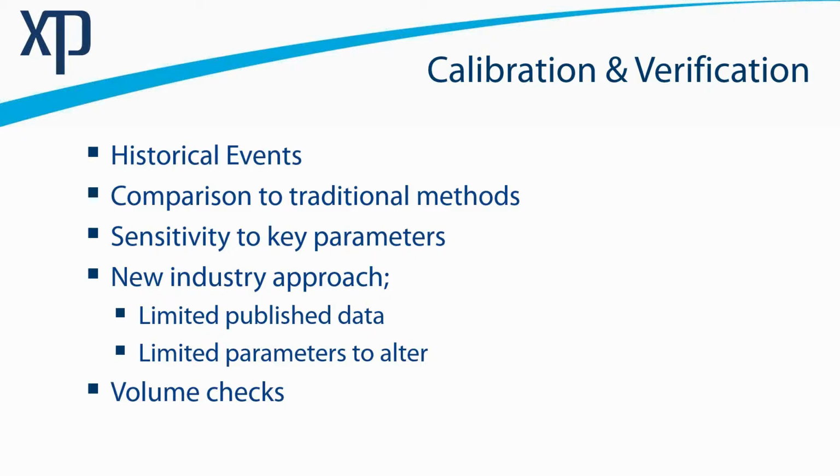In any modelling, it's very important to understand what your most sensitive parameters are. So sensitivity test your parameters. If your infiltration into your ground is a dominant factor in getting your modelling right, then that's what you should be focusing on. Your Manning's n values could be relatively fairly trivial. But if you're in a low infiltration area, your Manning's n and how you treat it at shallow depths could be very, very important. So it's very worthwhile to get a good feel for what parameters really have a big effect on your model results. And when you're calibrating or comparing traditional methods, you should focus on those parameters.